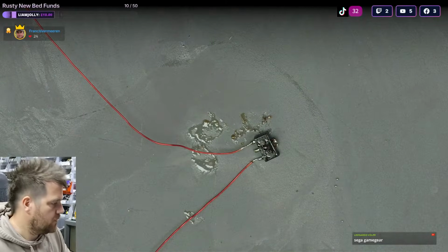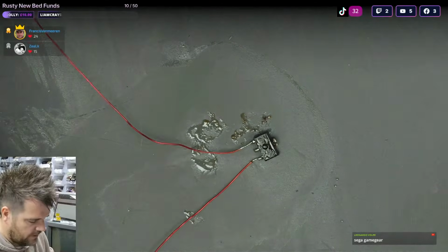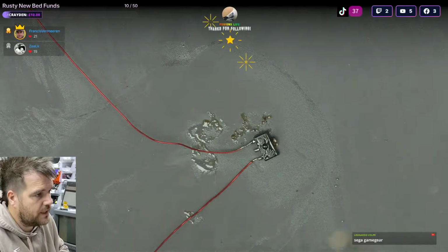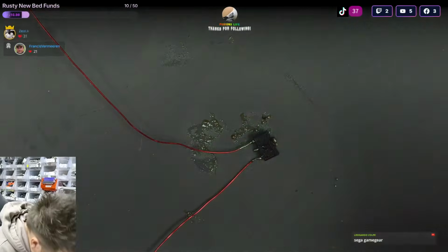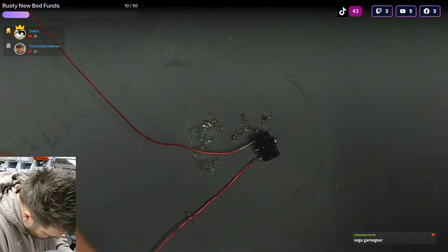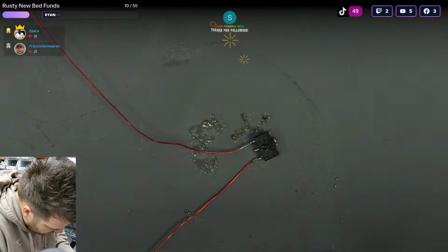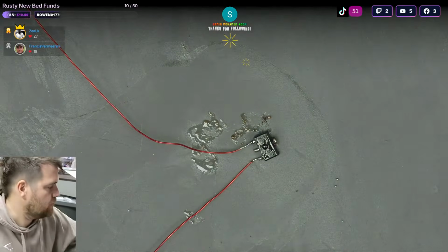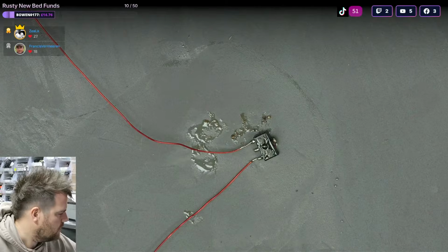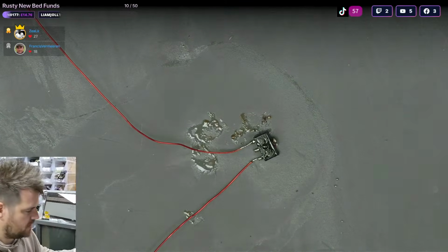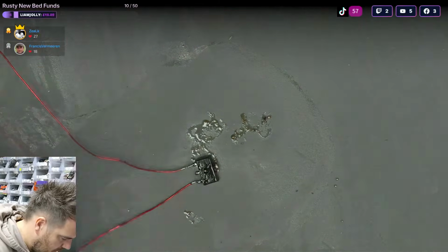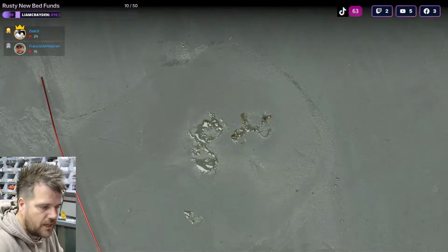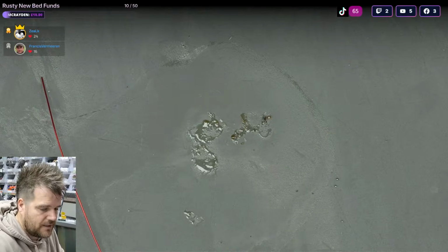Do you get game audio as well? Basically, the first checks I'd do either way on a Game Gear is turn it on, make sure you get red light boot, so make sure your red light's coming on and staying on, and if it is, do you get game audio? If you've got screen issues, ignore the screen for now and see if you're getting game audio, and that basically tells us if the console's running properly. With game audio and red light boot, then it's specific to the screen. Otherwise, I wouldn't even bother diagnosing a screen until you've got full working game audio and a red light, because the screen will just do anything random until that point.